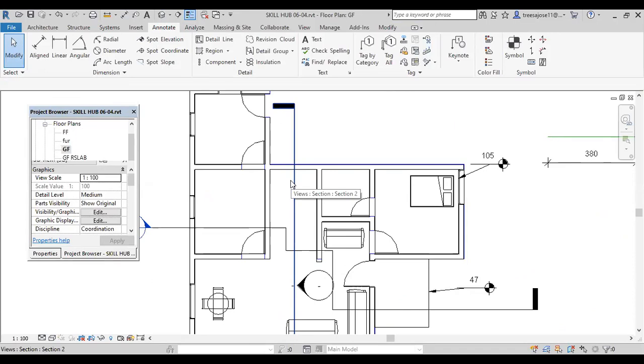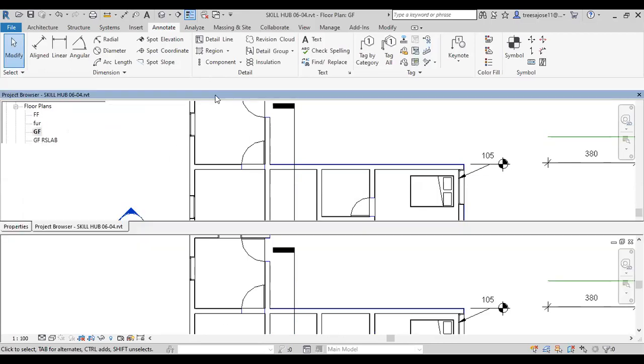That is why in the case of a ceiling plan, while we are working with the ceilings, even though we are placing the ceilings, that particular ceiling is not visible in our floor plan. That time we have to change the visibility range. That means I want to see the window position in my plan also. That is also independent for individual floor plans. Okay, ground floor, then you go to the visibility range.